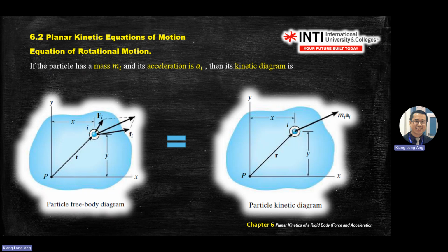A rigid body has rotation, all this. Again, we are looking at A. What is A linked to rotation? For A, you have normal and tangent directions. There's an equation for normal acceleration and tangent acceleration, linked to omega and alpha. So in the normal direction, AN equals omega square R, and AT equals alpha R. Still the same, but again, we are repeating the F equal to MA diagram.